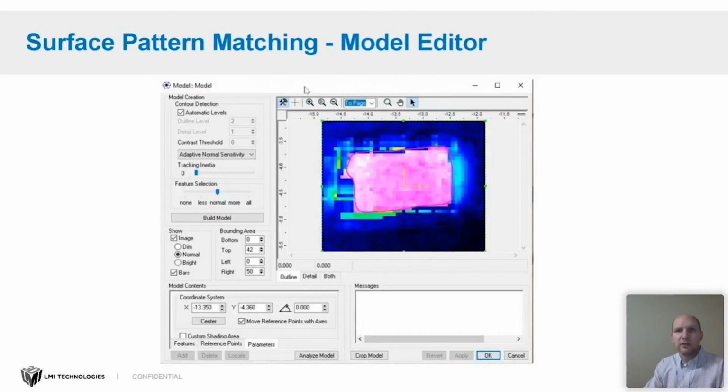And then if you need to tweak your results further, we've also included a new utility in the utilities package. So this is a Windows application that allows you to edit your model as well. So you can actually edit the model that you've generated from the tool, and add and remove edges, change the detection thresholds, and just perform any other edits directly with the part in the field of view here in this separate tool. So that allows you to just perform additional editing that might not be possible within the UI itself. You can do that here. And I would say in most cases, you might not need this at all. This is just for cases where you do want to tune your model further to increase your matching quality.